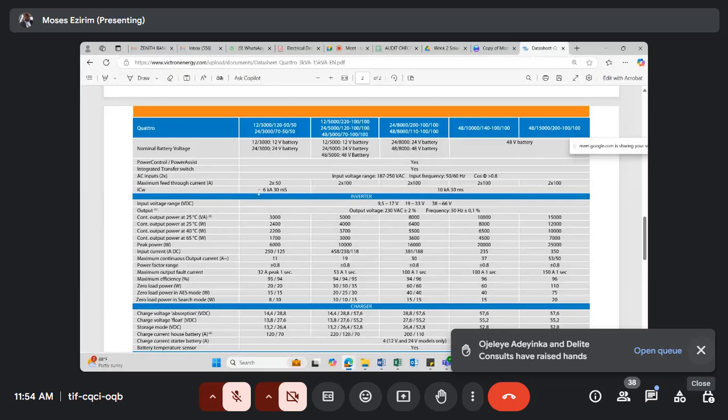Now, do you think I can use this data sheet? You can see nominal power of the PV. How many of this one do you think I can use? You can see this is the total nominal PV power, 1160. So I can actually use 5 of this. Remember, I can actually series 5 of this.